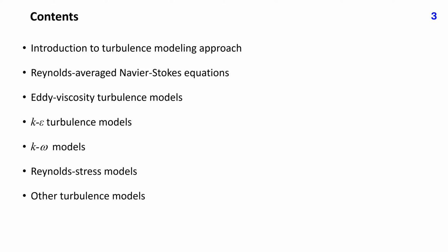Turbulence models from the K-epsilon family require the solution of an additional equation for the dissipation rate of turbulent kinetic energy, which is used to determine the length scale. Another family of models solves the equation for another variable, omega, to compute the length scale. Both equations and their modeling are presented.